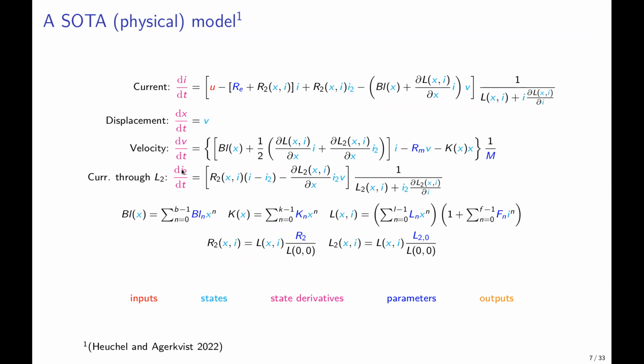this is a model that uses something called an L2R2 model. So you have some additional modeling states, but they're not directly measurable. And then you have some nonlinearities, for example, the force factor. So the proportionality factor between current and the force. And then you model this as a polynomial in the displacement. So maybe it's really high at the center position, but if you push out, the force factor gets lower and you have less force. And this represents then these nonlinearities.